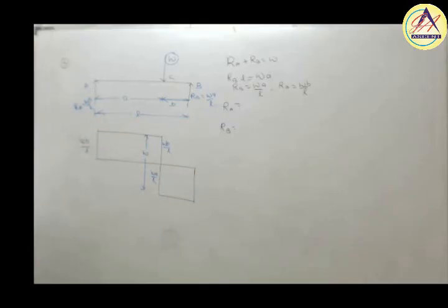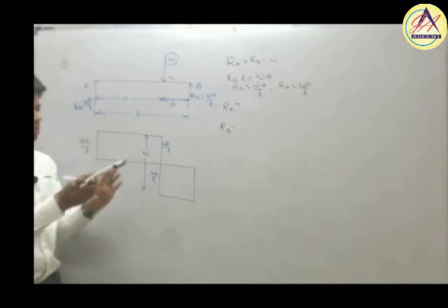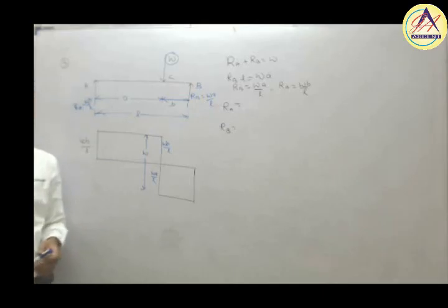Clear or not? So this is a shortcut, obviously valid for point load only. You can directly plot the shear force diagram in case of point load, only if only point load is acting.